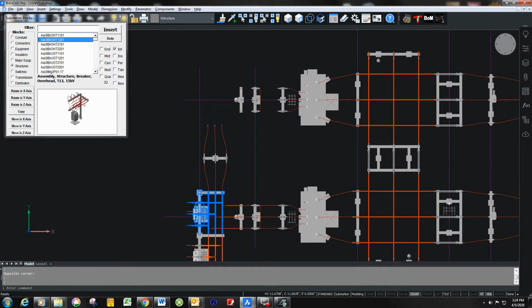Okay, this is an overhead, and it's got this bus over bus. So we're going to change to an option that has, here's an underground option, but it's the same bus over bus. We're going to change to an underground exit that has our main and transfer bus on opposite sides of the structure, so they're not above each other, which makes maintenance much easier.